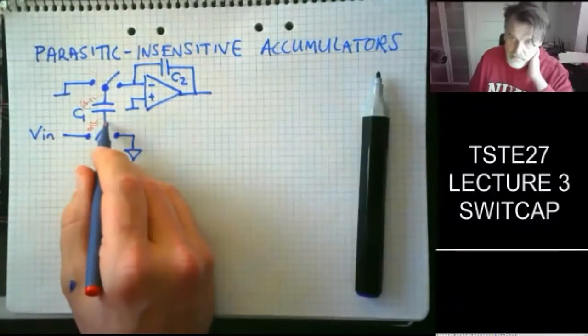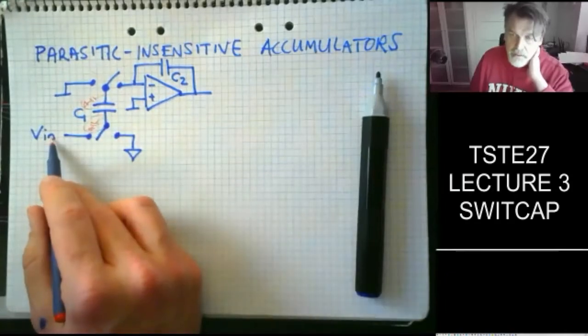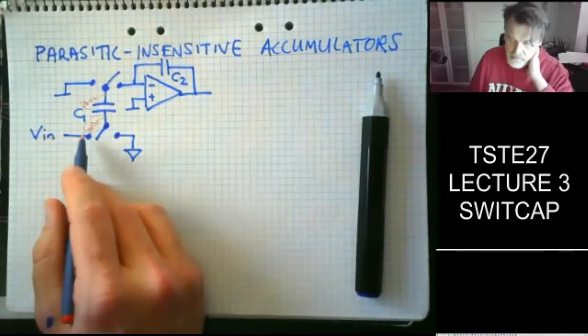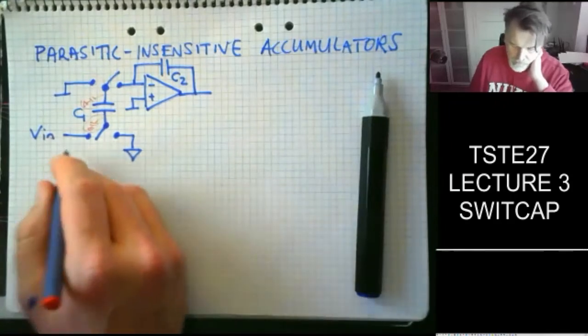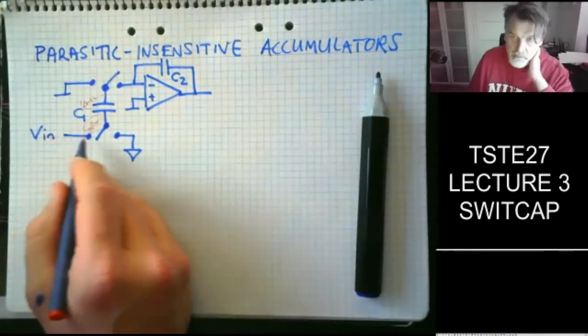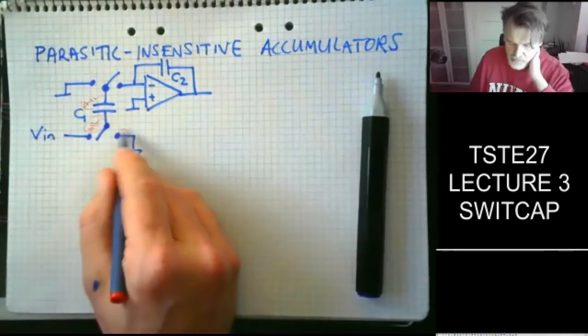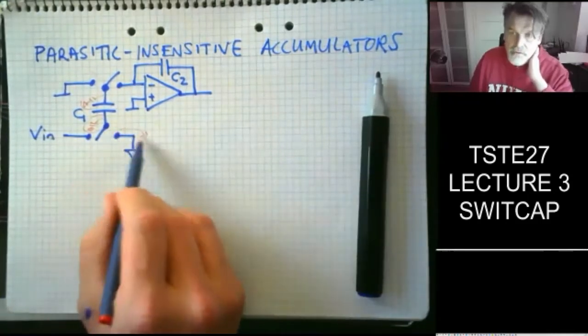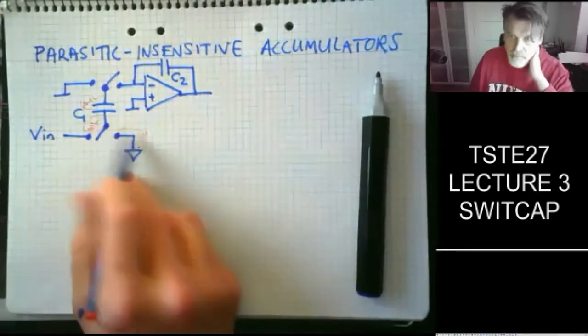The capacitor on this side of that plate will be connected to V in during one of the phases and to ground in the other phase. So either I will charge with my ideal voltage source a certain net charge, and then that net charge will just be flushed down to ground during the next phase. That doesn't influence my transfer function.